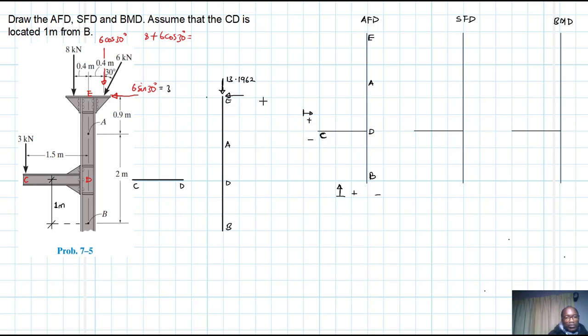Okay, and then we had this other force here, this horizontal, which is just equal to 3. Okay, because sine 30 is 0.5, so this one was a 3. And we also had the moment here. We had the moment that we calculated about E, which is a point along the neutral axis. Neutral axis is an axis where the longitudinal stresses as well as strains are equal to 0. Okay, so we had this moment because these loads are eccentrically loaded, and therefore they are going to cause a moment about the neutral axis.